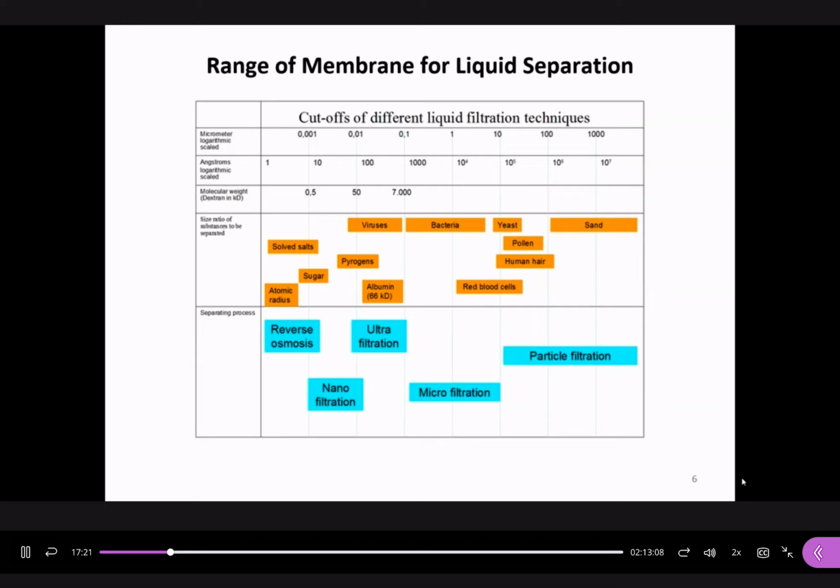Right, to think how large the virus is. So virus very small, and we can use ultrafiltration, right? But very tight ultrafiltration to remove viruses from water, right? So we have viruses in water, okay? Even drinking water, right? So our purpose is to remove these waterborne pathogens, right? Then even smaller, some molecules, right? Some molecules, sugar molecules, like the drugs you take, right? Or the hand washing solution, disinfectant, right? We can use nanofiltration, and finally reverse osmosis to remove salts, right?